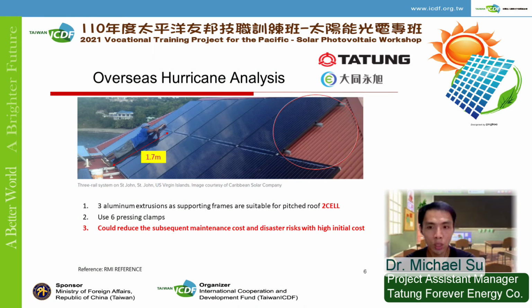As mentioned previously, there's the 4 and 6 anchor point method for diagonal roofs. Now, usually in foreign countries, they would use the 6-point method since their module is bigger. Take this guy in the picture for reference. Let's assume he is 1.7 meters tall. This module he is laying on will be approximately the same length. So we will add an additional anchor point in the middle, making it 6 anchor points in total.